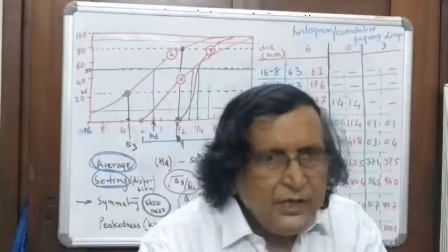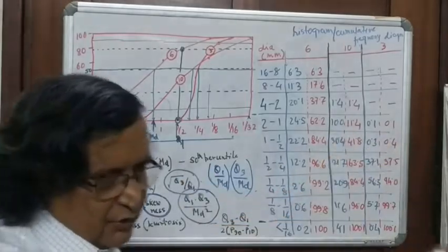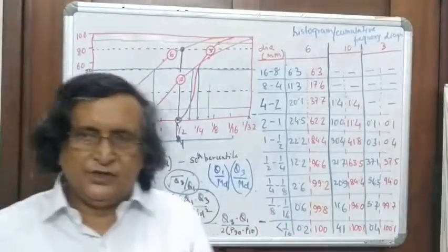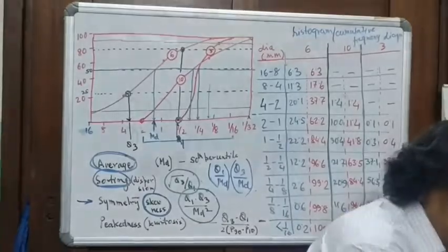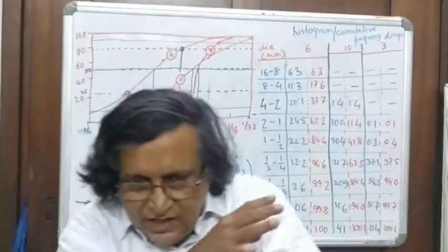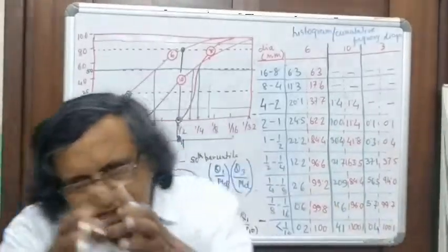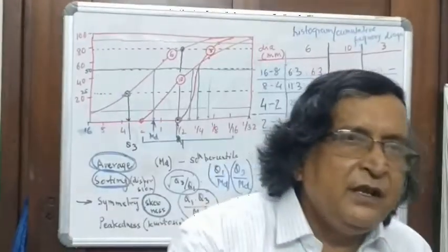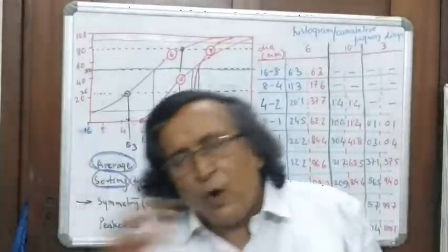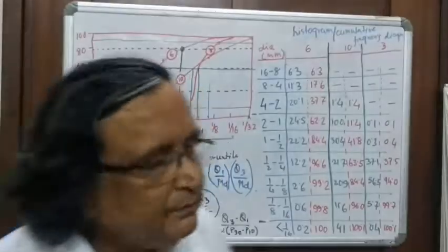As you disperse, you can have decimals and values greater than 1. So one is for negatively skewed and one is for positively skewed elements. In one, the finer size materials are skewed up, and in the other, the coarser size materials are skewed up. So all these parameters give you a variation in the size distribution of the sediment. And once you have the size distribution of the sediment, you can try and find out what was the dynamics of movement that created these sediments, right?